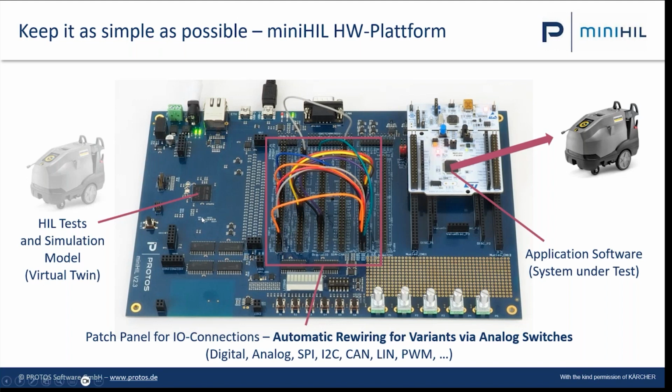And one level further up, you need, of course, software to simulate the complete environment. So, for example, in order to bring your system under test into the right state where you actually can test, you need to simulate a motor, because if the motor is not attached, you cannot really run your system because it fails immediately. So we simulate the motors, the sensors, the complete environment.